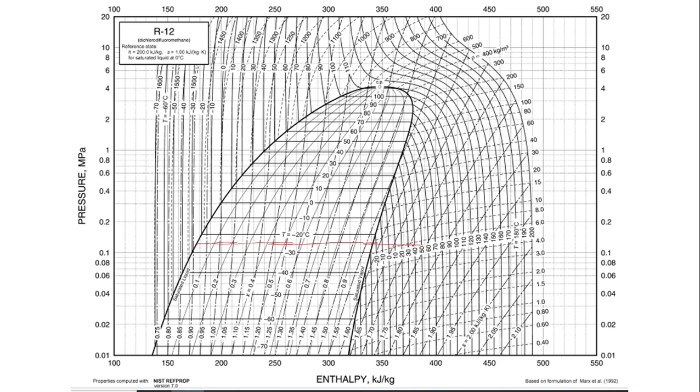With respect to that there will be some pressure. Now, as you know there is superheating by 5 degrees Celsius, so the exit of the evaporator will have a temperature of -20. This is the -20 line up to here, and then it follows the curve over here. Wherever this line intersects this particular evaporator pressure line, you get point number 1 over here. Now the next is the temperature of the condenser given.